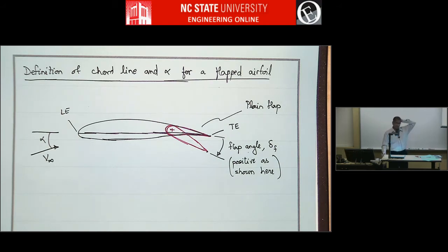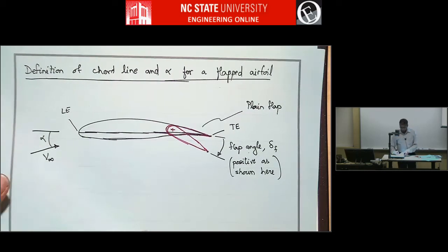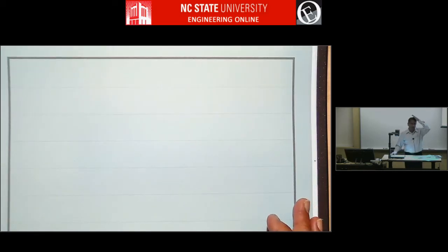Yes? I have a question. This is from some of the work we did with flaps that extend, instead of plain ones, like slotted flaps. You actually end up with a longer airfoil shape. We took the longest value so that when you were nondimensionalizing it, you weren't ever going above 1. Would you go with that, or would you still use the closed one? So the question is, when you have a slotted flap, what do you use?